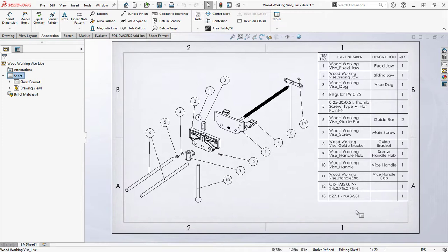Hopefully you guys have learned a lot about drawings here in a short amount of time, especially if you've never worked with drawings before. You've seen how to create a basic 3 view of a single component, add 2 types of model information, driven and driving dimensions, and you've learned how to create different annotations and notes and change drawing settings. So you hopefully have learned a lot to get going and create your own drawings in SOLIDWORKS. Hopefully good enough to accurately describe your parts to whomever you'd like to.